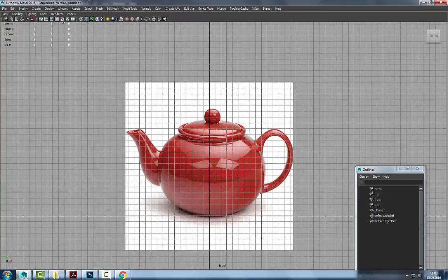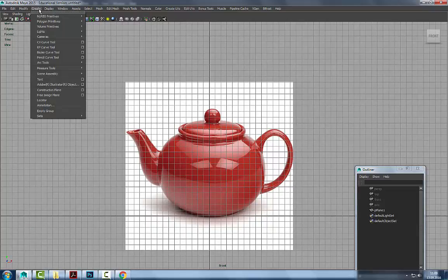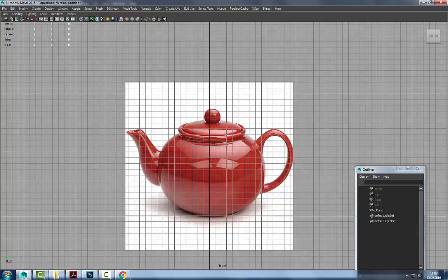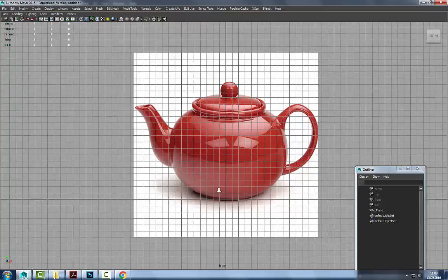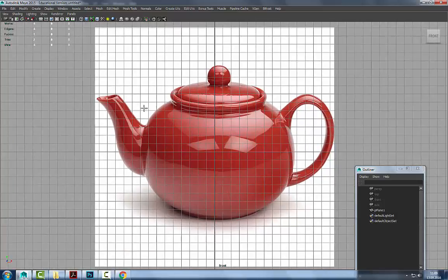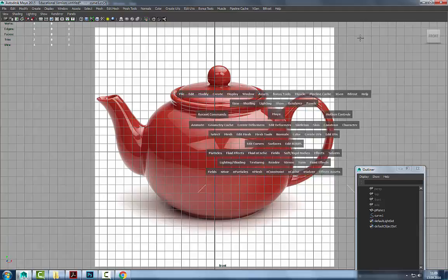This is what I want to show you. It's not an orthographic image again, so there is perspective. So we're going to have to guesstimate the shape a little bit. That's fine. Like I did this morning, I can now draw an actual curve using the CV curve tool. This looks like a fairly easy shape, but let's just try it. I'm going to hold X to snap to the middle of the grid for the first curve point, and then start drawing the curve.